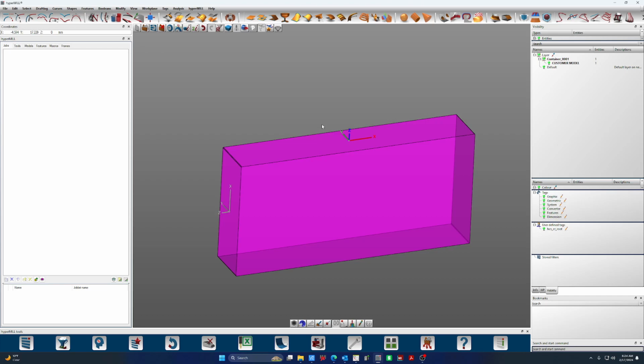If you have a part that you know is a round 3D solid or model, and you set the tessellation tolerance to be really high so it looks like a friggin' octagon on your screen, you are going to get a toolpath that creates a nice round 3D or 2D shape. It is not going to give you an octagon, and that should be immediately apparent in the code you're getting.